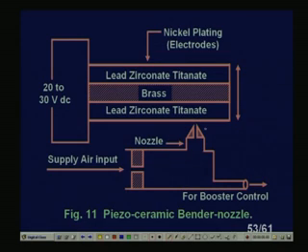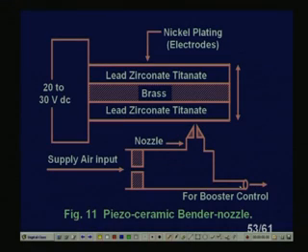away from it. So, this will give you the booster output, this is a pilot pressure, which is sensitive to the booster control. This pilot pressure will be a function of this DC voltage we apply to the flapper nozzle at this ceramic. And this voltage, again, is a function of the current which is coming. So, whatever pilot pressure, back pressure, I am getting here, that is proportional to, or a function of, exactly the current which you are getting.